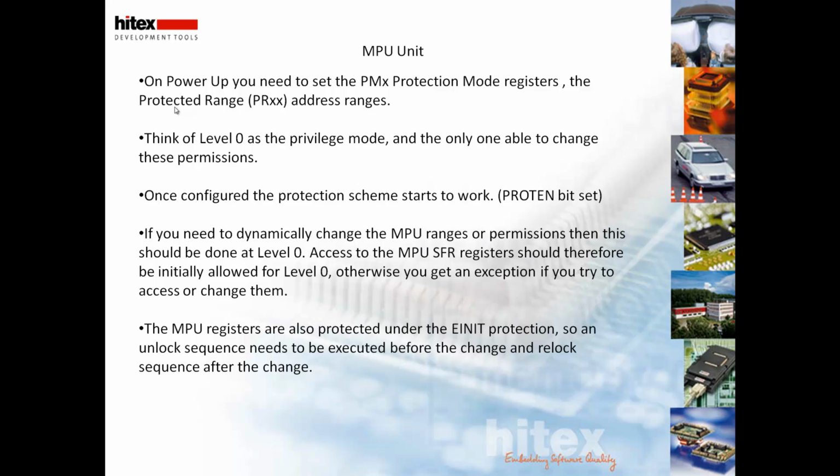Once it's all configured, we can then enable the PRO10 bit, which is in the PM0 register, bit 0. If you need to dynamically change the MPU ranges or the permissions, then that should only be done at level 0. So access to the SFR registers should initially be allowed for level 0, because obviously these registers are memory mapped, so you need to make sure that level 0 has access to them. Otherwise you're going to get an exception if you try to configure them.